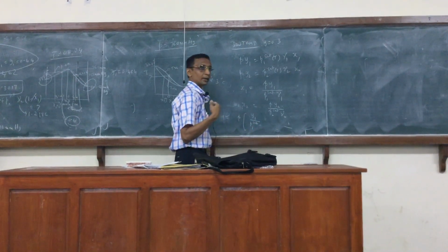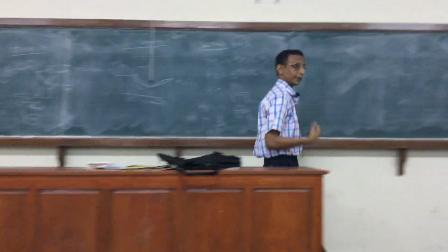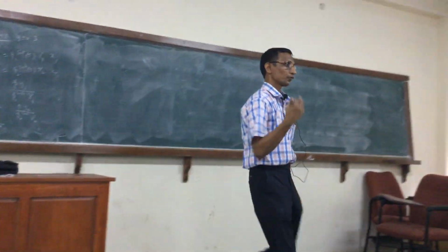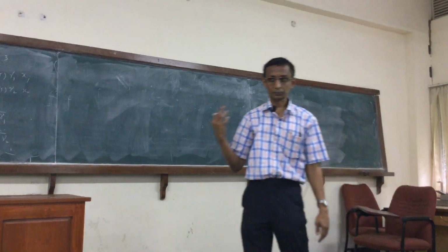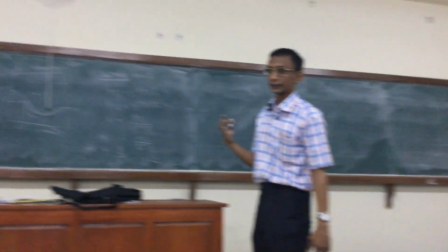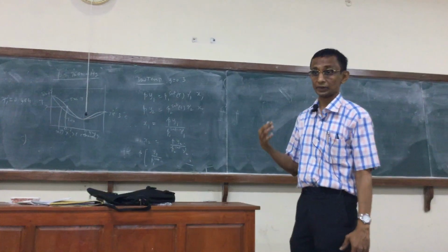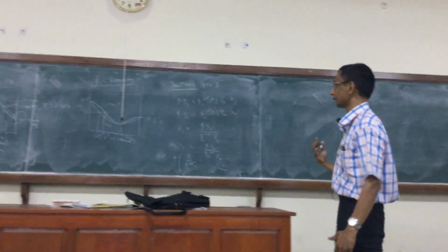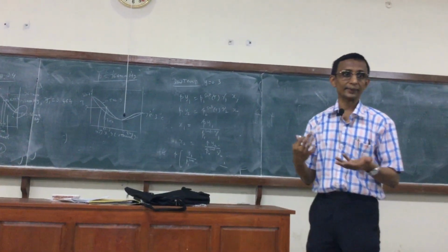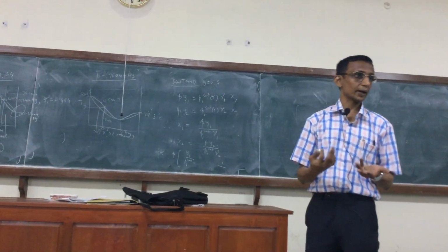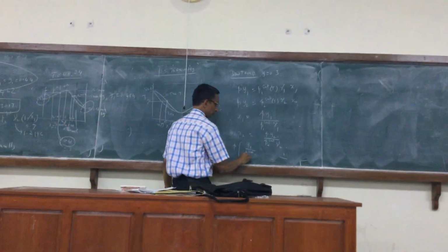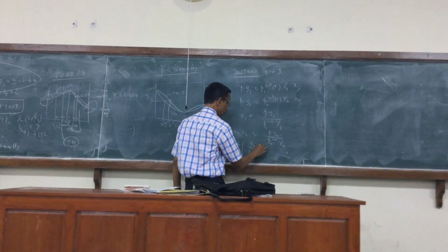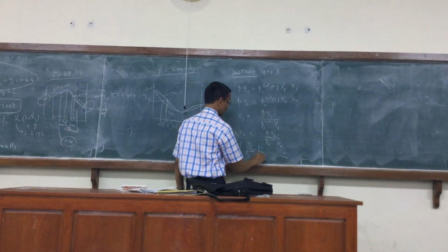So we see that the procedure for this is almost identical to that of the ideal case. Procedure is the same, but you have to now deal with the gamma, which is of course dependent on both x and T. So anyway, we are going to assume an x and T. You calculate the gamma at the assumed value of x and T. So y1 by P1 sat, and you will have in addition, this is the only difference.